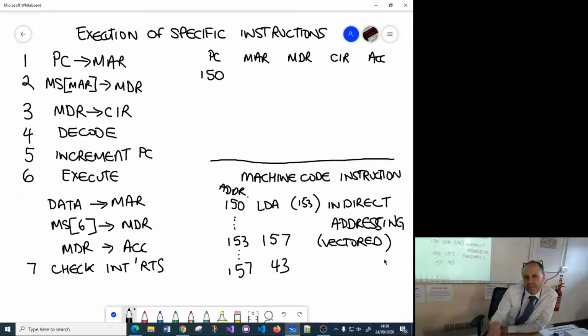If the keyboard interrupt handler had to be pre-known and pre-written, we wouldn't ever get anything to work. What if I plug in a fancy keyboard that needs its own routine? I would have no way of changing it. But what this sort of addressing system allows us to do is to say, you put your routine at that location. We will use that data at that location to go off to your routine. So when an interrupt occurs, what actually happens is that it generates an interrupt vector that goes to a specific location and looks for the data that's there. That data can be changed.